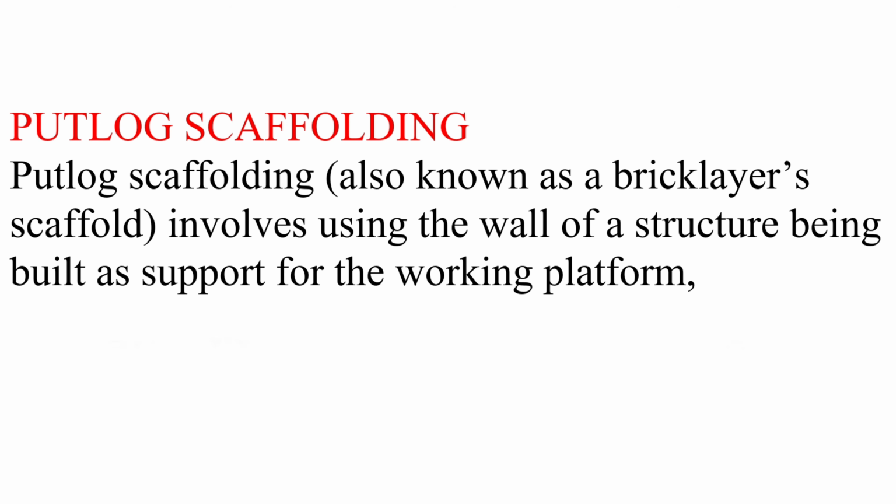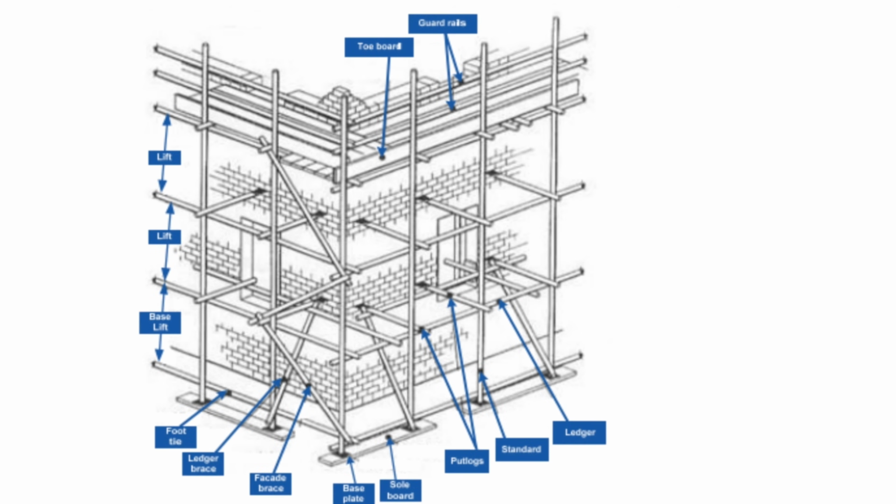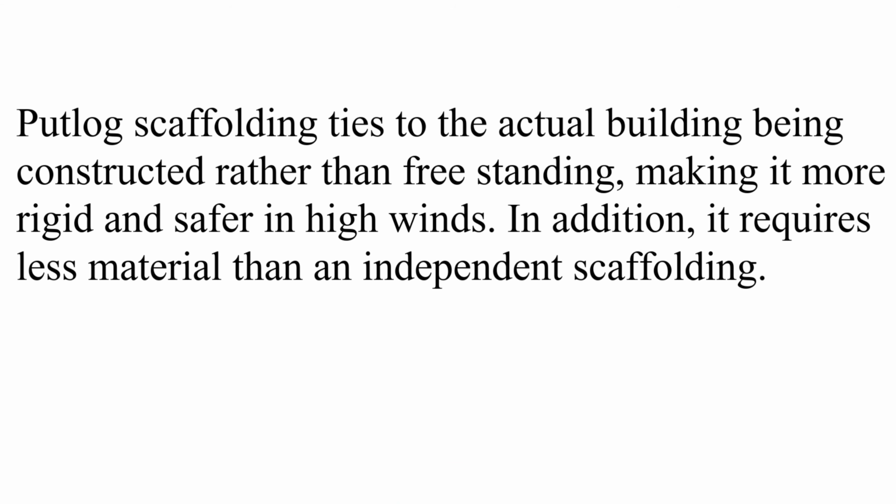PUTLOG scaffolding. PUTLOG scaffolding, also known as a bricklayer's scaffold, involves using the wall of a structure being built as support for the working platform. PUTLOG scaffolding ties to the actual building being constructed rather than freestanding, making it more rigid and safer in high winds. In addition, it requires less material than an independent scaffolding.